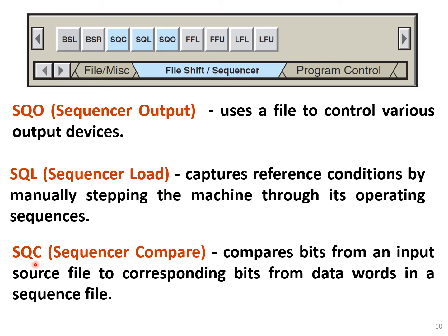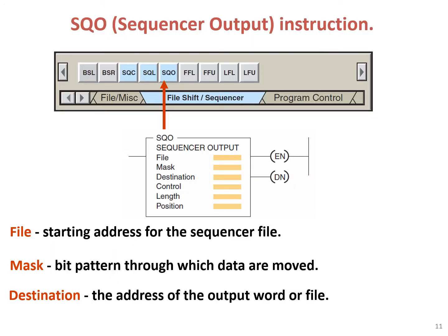We will discuss SQL and SQC later, but first we go to SQO because it's the most common one, plus it is the most intuitive one. We already discussed mechanical devices similar to the SQO, and we want to see how we could use SQO in PLC programming. So here we have the SQO instruction.